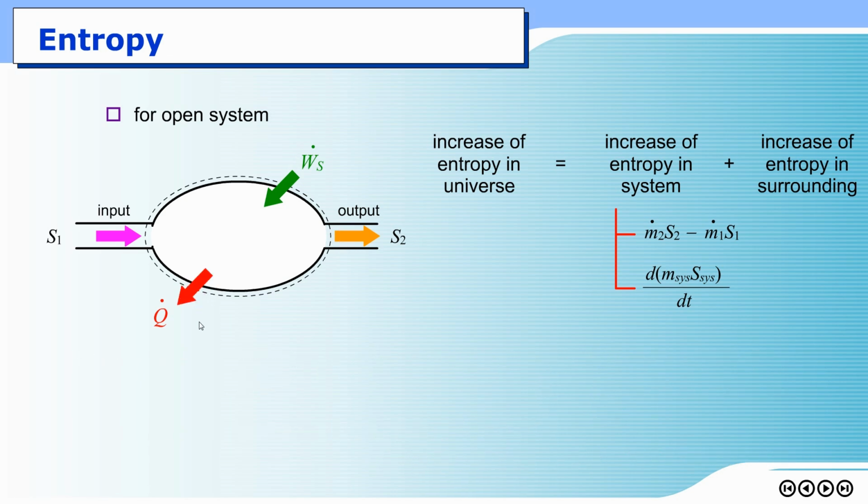On the other hand, for the entropy change, or increase in entropy, in the surrounding, it would be easier to understand if I flip this sign. If the system releases heat to the surrounding, normally we say that the mass of the surrounding is not changed. The surroundings are usually very large, and the properties are not changing. When the system releases energy to the surrounding, we learned from lecture 4a that heat can make a change in entropy, but work does not make any change in entropy, right? So we consider only heat here.